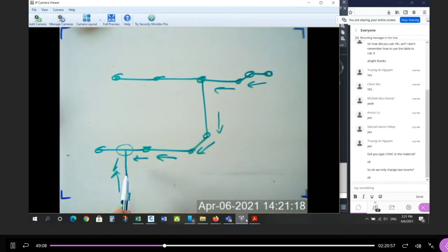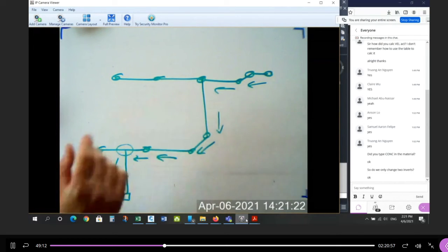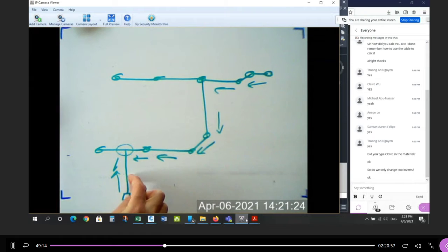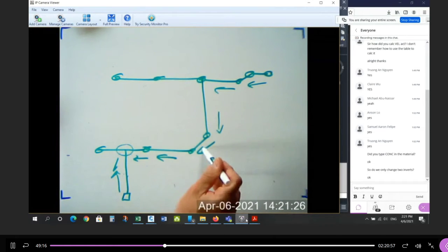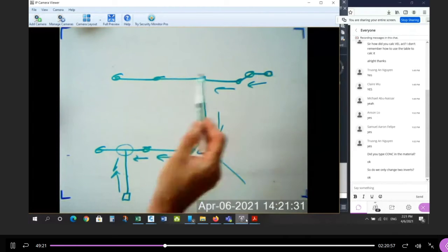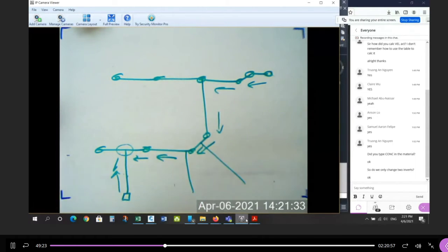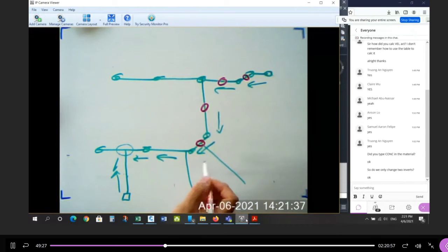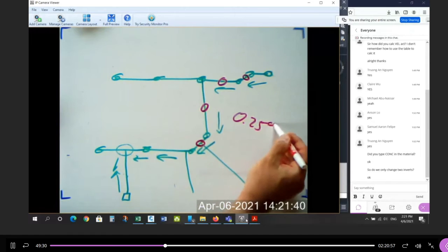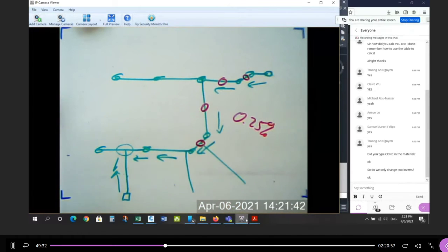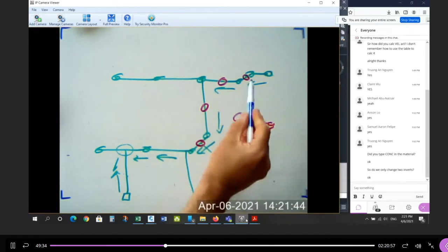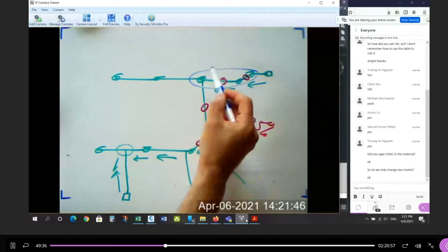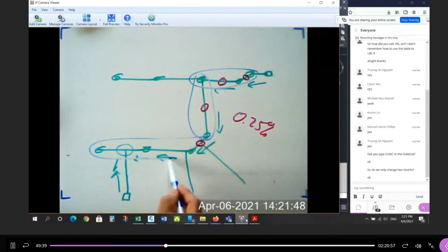If this is too low, we have to find a way of driving the sewer system down or raising this pipe up. And the two pipes in the corner, this one and this one, require a little bit of both. I have to flatten the system. Which pipes are we flattening? We're flattening 1, 2, 3, 4. Those are the ones that are going to be 0.25%. And then we're going to recalculate all the inverts from here all the way to the end of the site.